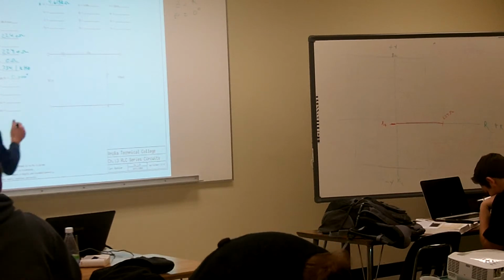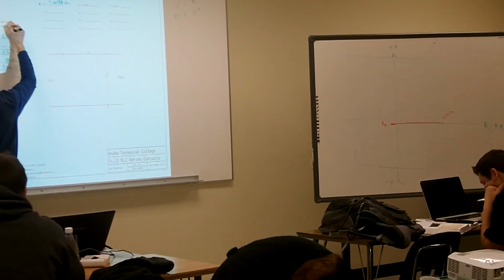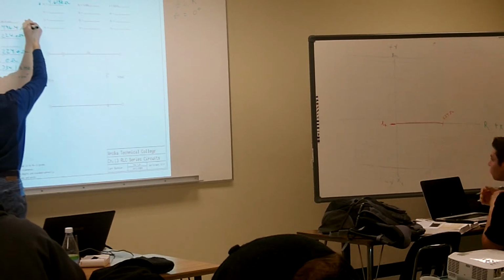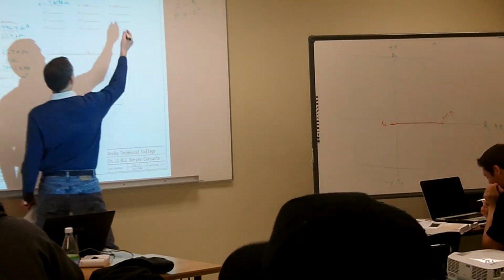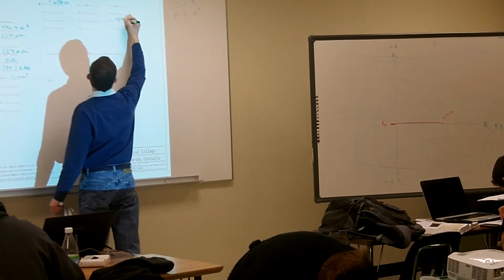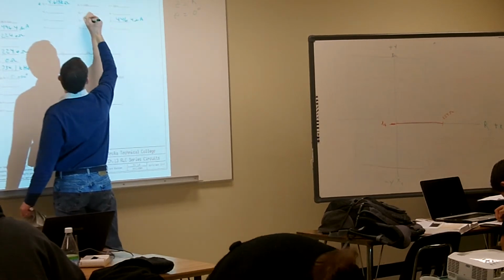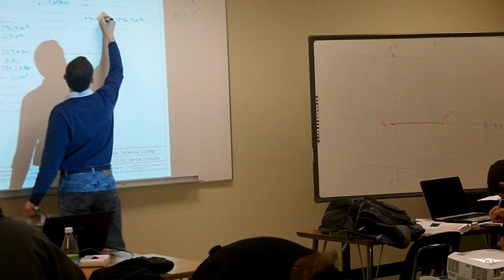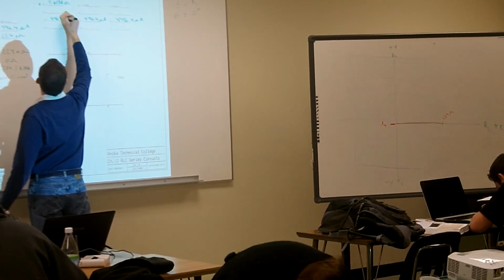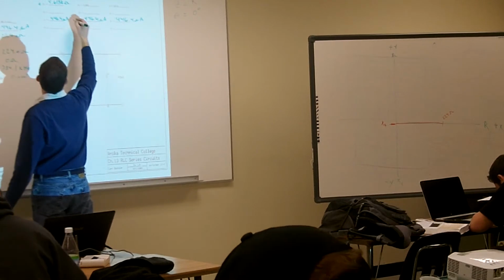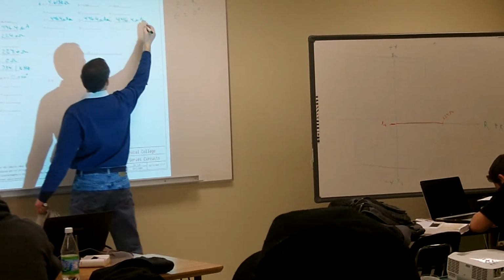446.4 microamps. Say it one more time. 446.4 microamps. Everyone agree with that? Yes. All right, good. Then we can fill that in all over the place. We're going to put in 446.4 microamps here, and 446.4 microamps here. We also want to make sure that we keep the same units, so make sure we have amps AC, so we know that it's already an RMS value.